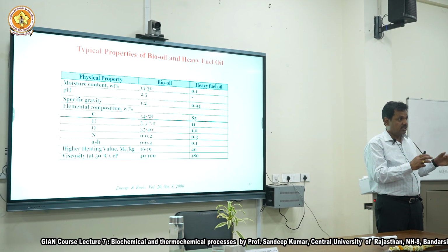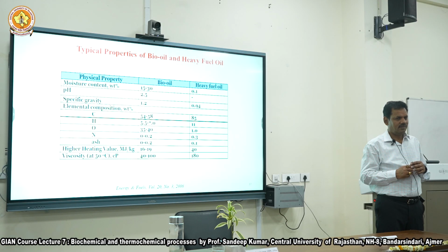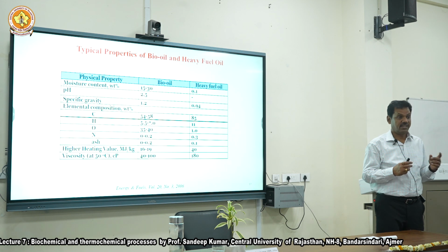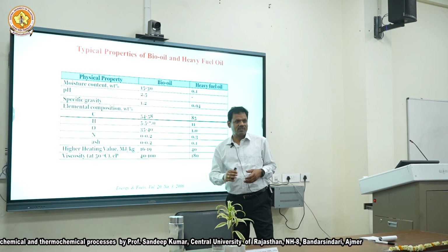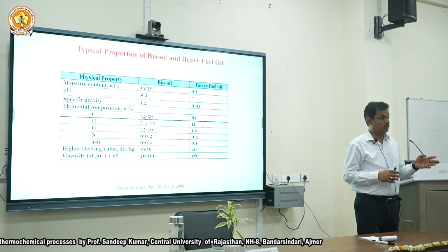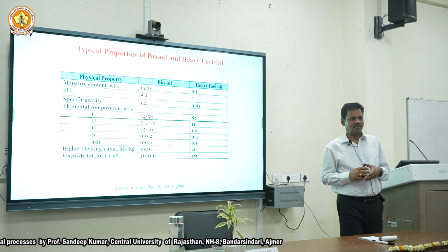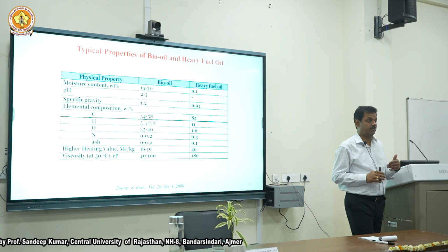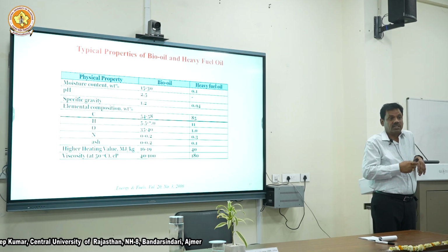So we pyrolyze something to make oil, right? We expected to have a heating value closer to oil. Take any pyrolysis oil, you will get 20, 16 and so on. Why should we do this? Turning it to liquid, there is no way it gets close to what we want. So why do we do that? What benefit do we get doing pyrolysis if we are making oil?